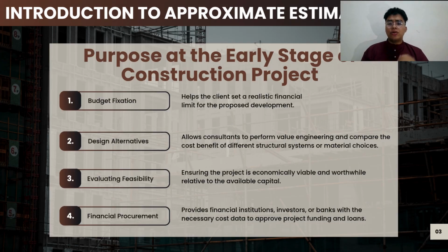Next, let's look at the four core purposes of approximate estimating during the early stage of a project. First, we have budget fixation. It helps the client set a realistic financial limit for the proposed development, preventing unexpected overspending. Next, we have design alternatives. It allows consultants to perform value engineering and compare the cost benefit of different structural systems or material choices.